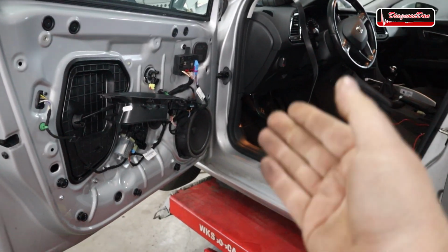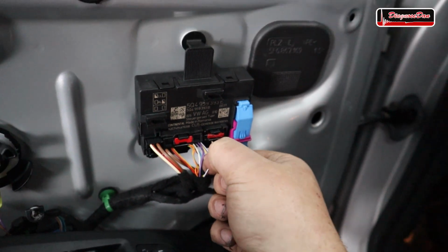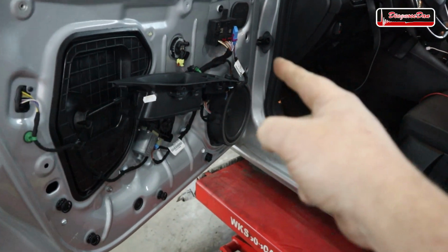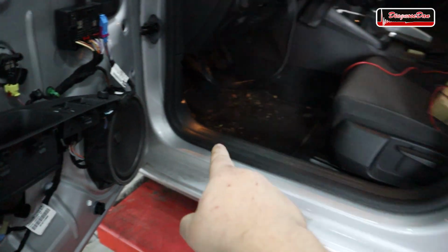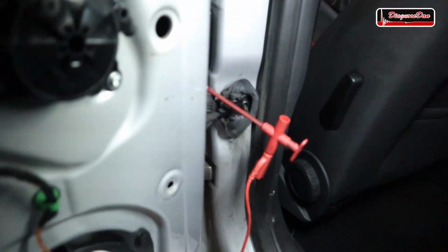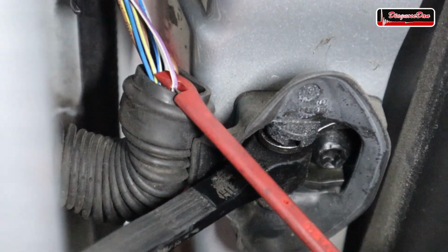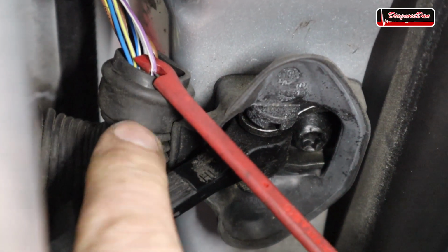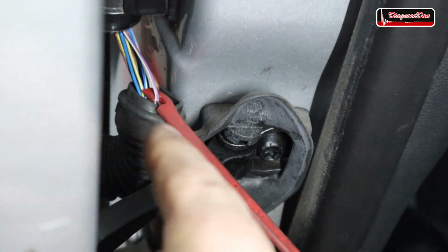Now we have come quite far with this diagnosis, but we're not there yet. This purple and white wire is broken somewhere, and when I say somewhere, I literally mean somewhere. It runs from that module all the way through that door, then through that hinge, then back down and all the way through the car, back up, then through that hinge again into this door. What I did is I tapped into that wire, that purple and white wire, as close as I could get before it enters the door. So I'm tapped into that wire right now, and there's a little piece left before it enters the door, but I pulled that. It doesn't appear to be broken there, but this is about as close as I can get before it enters the door.